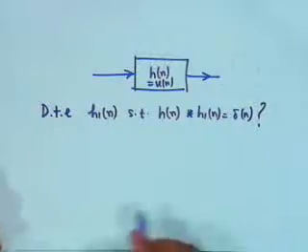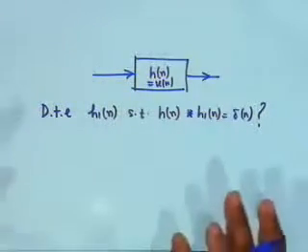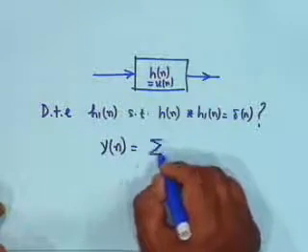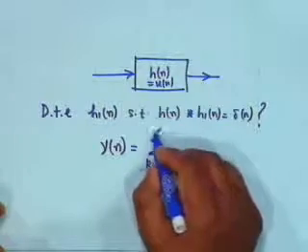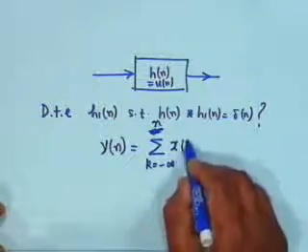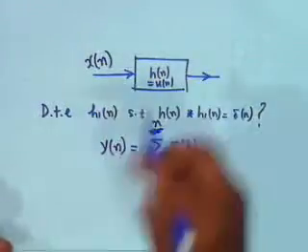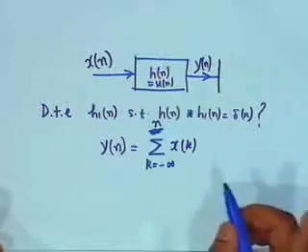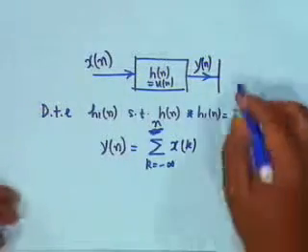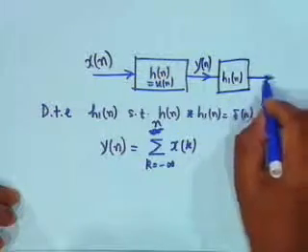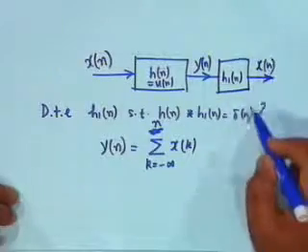This is the question. Now, instead of answering the question directly, that is, taking the convolution and trying to find whether delta n exists or not, why don't we look at the input-output relation, that is y of n equal to the sum over k equals minus infinity to n of x of k. You notice that if I input an x of n, I get a y of n, and if there exists an h1 of n, that is, if the system is invertible, then by applying h1 of n, I should get back x of n. So the question now can be reframed like this. Can I, from a given y of n, recover x of n? That will answer the question, isn't it?